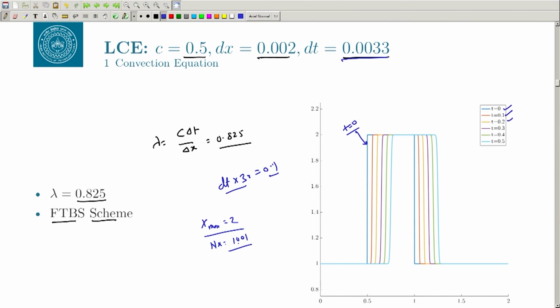You can see that now it is propagating and there are certain effects that you can see if you look very closely. You had a very sharp corner here in the beginning, but as it went to the right, you can see that the sharp corner became slightly more diffused. So, despite having no diffusion in the scheme, so there is no new del t by del x square term, you still have some diffusion, which you can see at these corners also. That means our scheme itself has certain diffusion, and that is what is called the numerical diffusion.